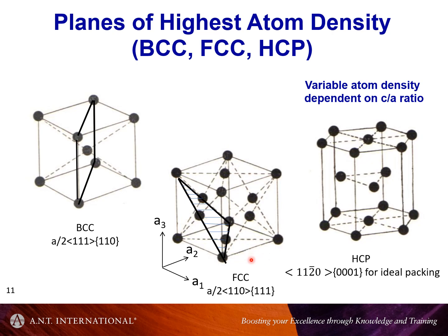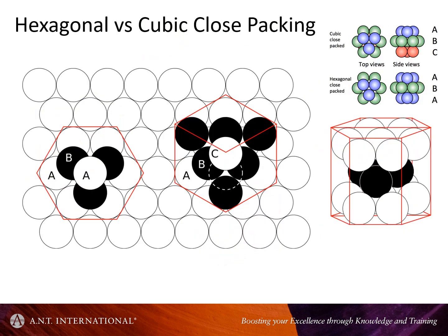The nickel stabilizes the FCC phase, and whereas iron would normally be a BCC structure, when you have nickel there, the common phase is austenite, and of course in nickel alloys themselves it's austenite. So what's the difference between a hexagonal metal and an FCC, a face center cubic metal? It comes down to the stacking.